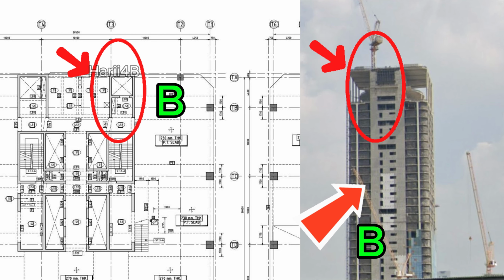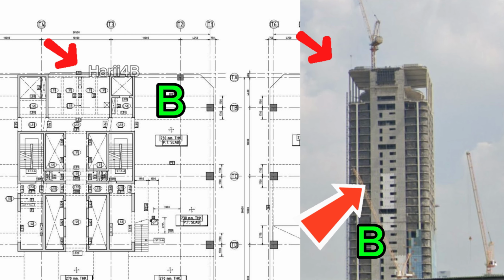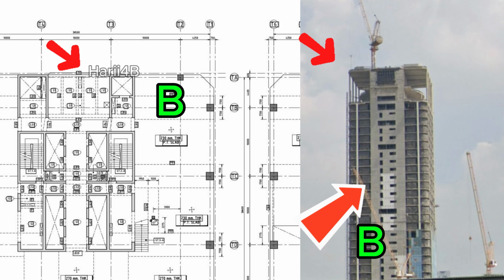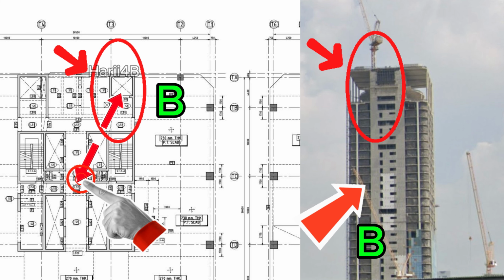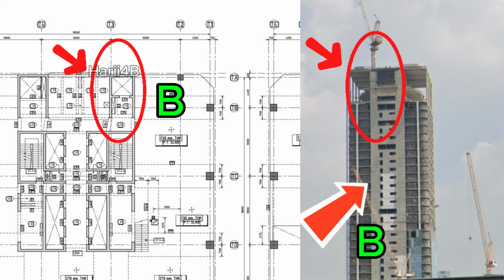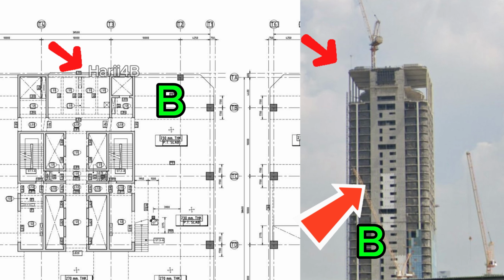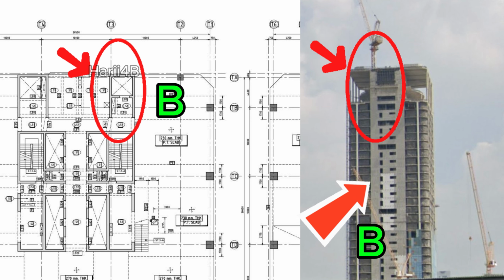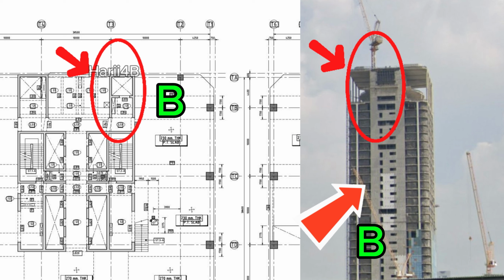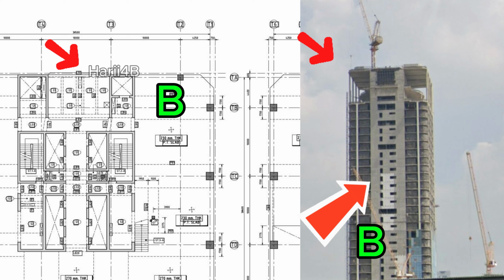The estimated compression stresses for both core walls are nearly the same. This is where the effect of the climbing tower crane came into play. The crane weight is offset from the center of mass of the building. This is generating an eccentric loading on the building. We can also consider that the core walls are tall, slender tubular columns braced laterally on each floor level. The tower crane being applied on top of the core wall will impact more on core wall B.